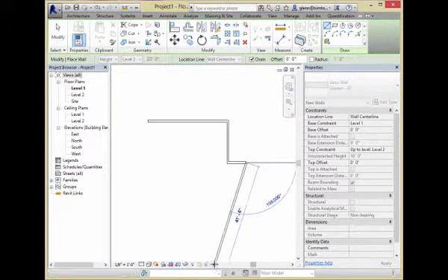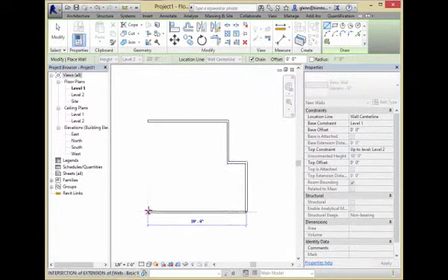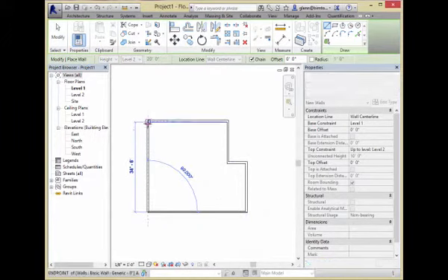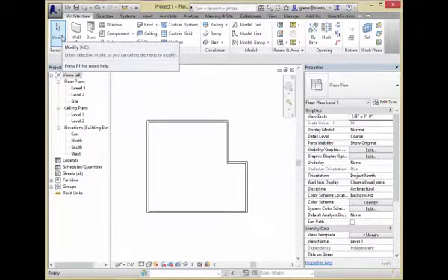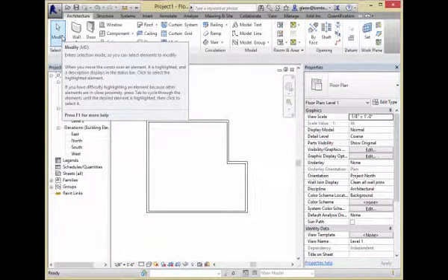Let me zoom back out again, Z-O to zoom out. I'll pop it back over here. I'll heal it back up, and I've got some basic walls. Now, generic walls, the cool thing about them is there's only one material, and it's even unadvertised what it is. So they're not too fussy about the notion of where your location line is.